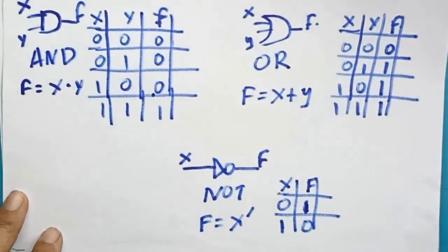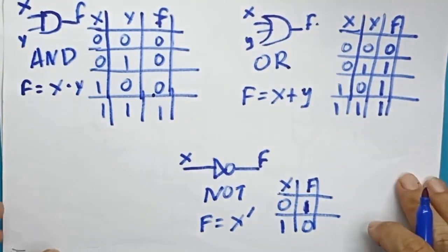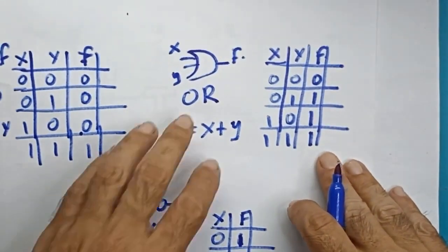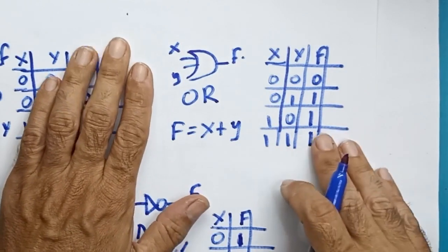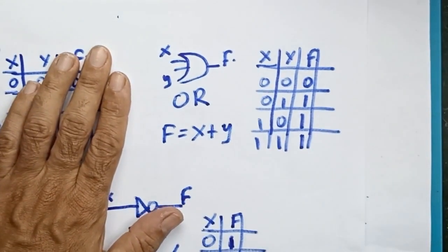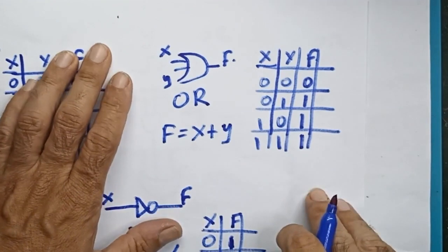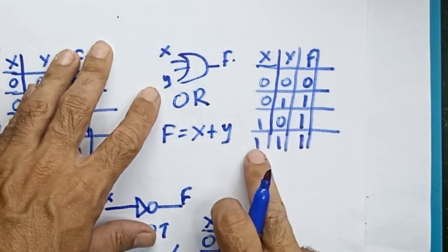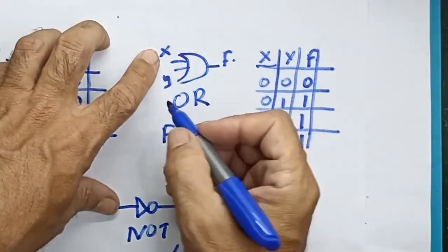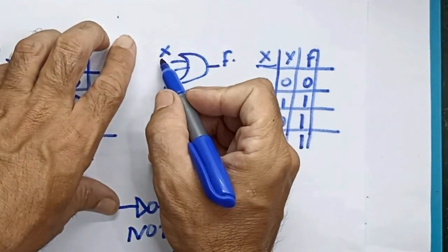In reality, it's a map of a digital circuit, which says what will come out at its output in the different situations its input may find. And when it has more than one input, it will output according to the combination of the situations its inputs may find. For example, here at the OR gate, X is its first input that can only take 0 and 1, and the second input is Y, which can also only take 0 and 1.